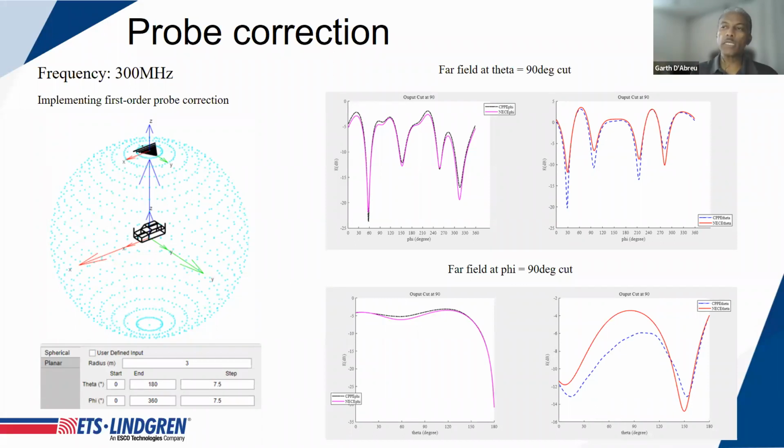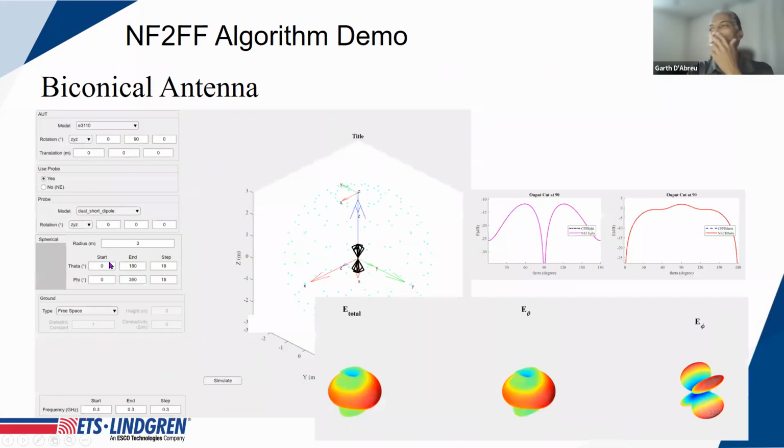In the real world, obviously that's not practical. Cars drive on a road, so there's a ground, a floor. There's an area below which you're not going to have much in the way of antenna behavior. You're also going to have reflections from that surface. So you still want to come up with some method of either measuring or modeling the behavior of the antenna when it interacts with these boundary conditions that you have in a real world environment.